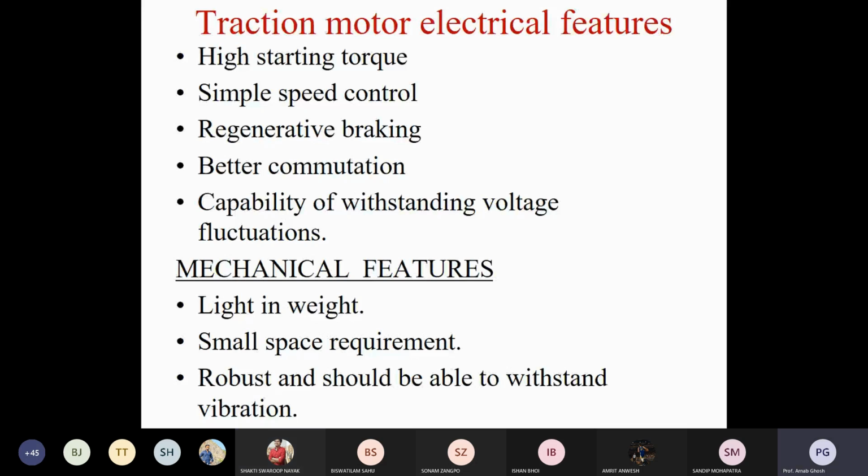So did you see regenerative braking in the lab? Yes, sir. In the machine lab. How was it performed? It was for a shunt motor, sir. It was a shunt motor, no problem. But how was it performed? Sir, we kept the field current and field voltage equal, and when we ran the motor, we suddenly stopped it.